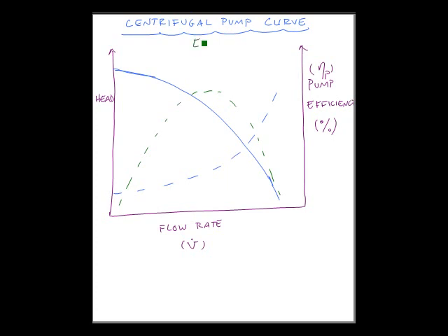Okay, well here's our figure 14-38. This curve here is my pump head utilized, so we call that pump head, comma U. This is my system curve. And where these two intersect is my operating point. That's the best case operating point. And they depend on the flow rate.